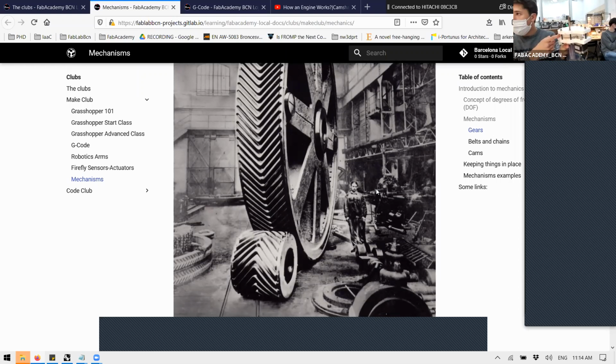So you put this big gear that is going to convert high speed, low force into high force, low speed. If I rotate here, you see that this one spins faster, of course, by every tiny move that I do here. If I do the opposite, I have to spin this much faster, but by a small force that I apply with my right hand, this one still spins. It's very difficult for me to stop it because I'm increasing the rotational force by the relationship of the size between this and this.